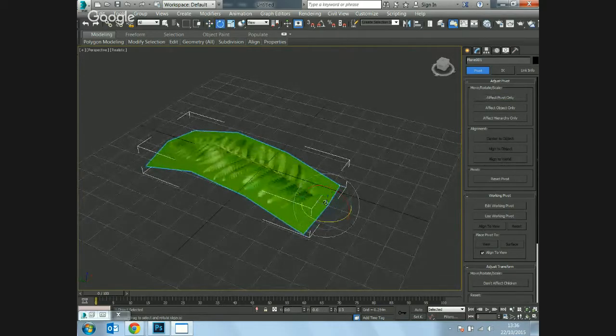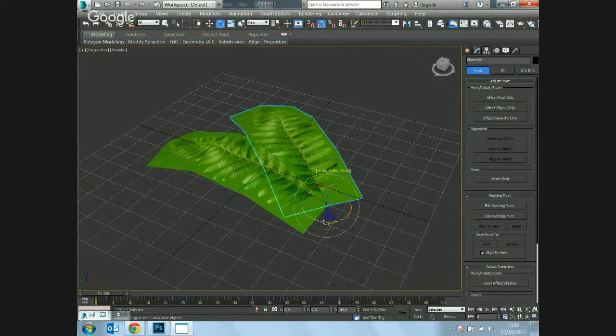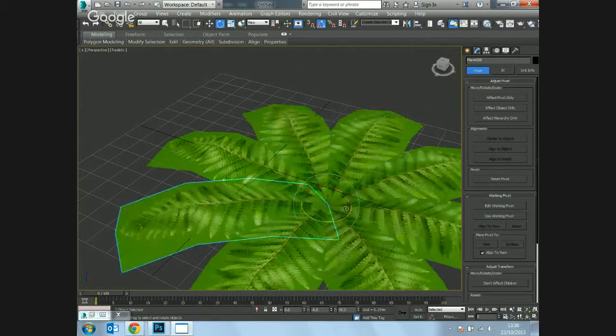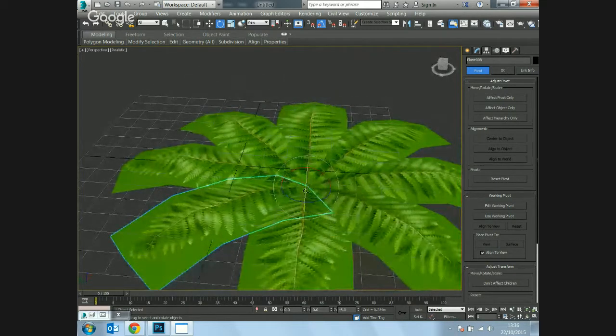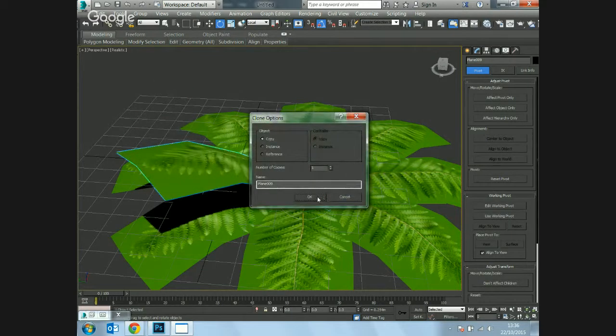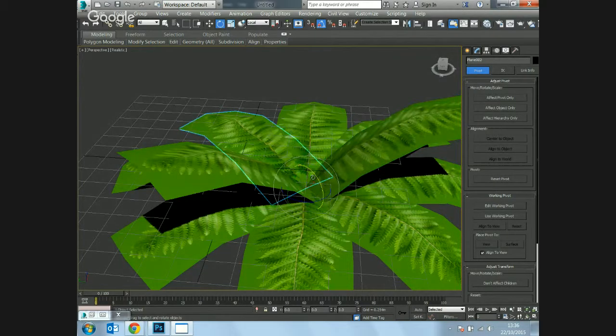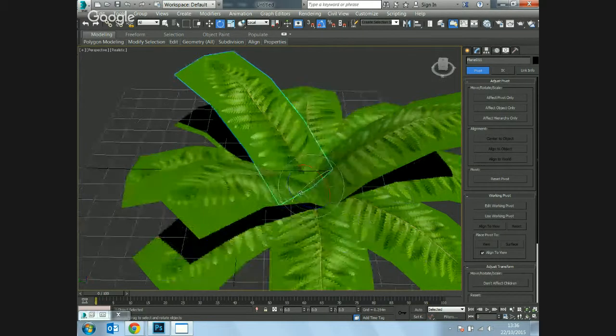And then I can use my rotation tool, hold down shift and make sure that angle snap's turned on. I rotate it by 45 degrees. I know I'm going to need 7 of them to get back round to the start. At that point, whilst holding down shift, and making sure that your section up here is set to local, I can lift some of these up as copies. We've got this.